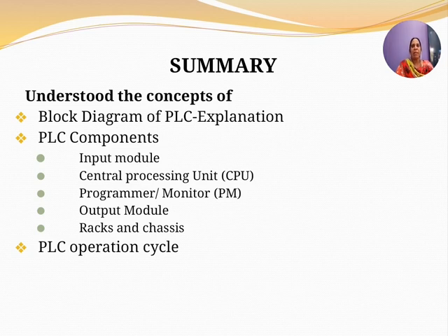Then the input output module. To sense the physical parameters like temperature, pressure, flow, etc., PLCs have an exclusive module for interfacing the input and the output, which is called the input output module. Input devices can be push buttons, switches, etc., to start or stop, and output devices can be electric heaters or valves or relays, etc. So the input output module helps to interface the input and the output devices with the microprocessor.